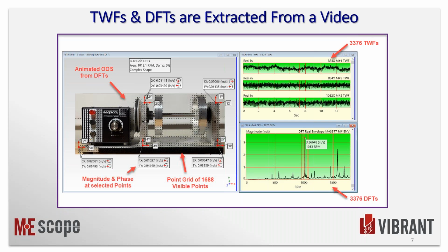inches per second. So again, this is something we can do with frequency domain. We can integrate and differentiate very easily the data. Whereas in the time domain, it's more difficult. There's probably 100 algorithms to do integration differentiation. But in the frequency domain, we have the advantage of just algebra, multiply or divide the data. So a video records displacement from frame to frame to frame. That's what the algorithm does that we have in MEscope. But here the data has been converted to velocity by simply differentiating in the frequency domain, multiplying by frequency.